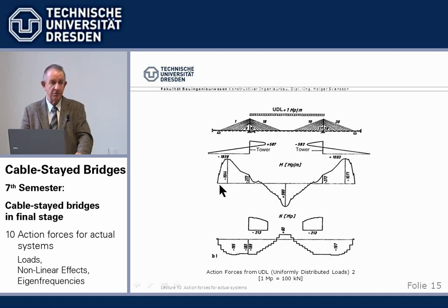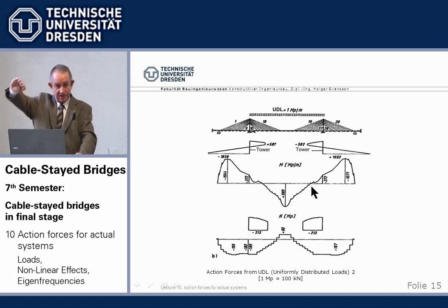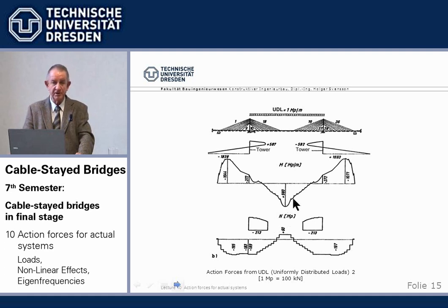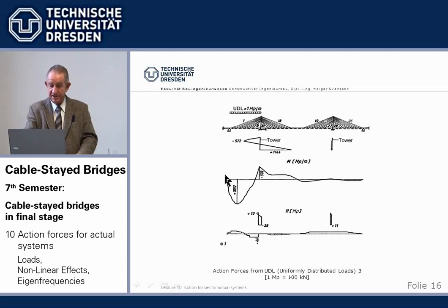Here you can always think of curvature. We have a positive curvature, clearly, in the center, so a big positive moment. And we have a negative curvature here, so we must have negative moments. I think it's easy to understand.